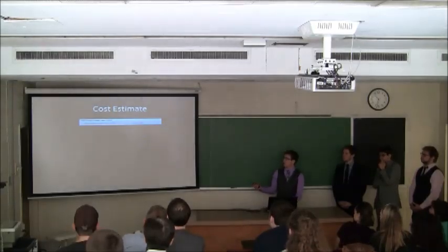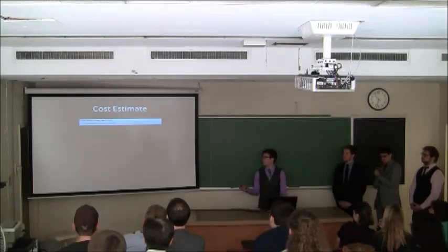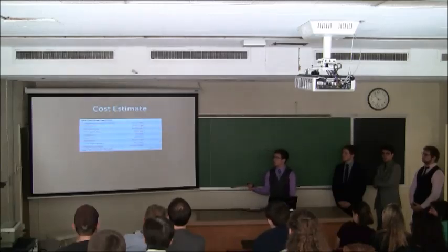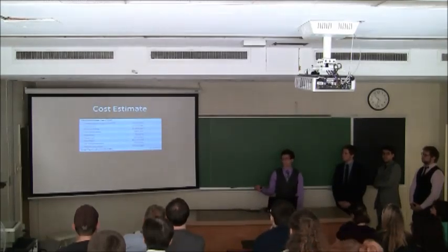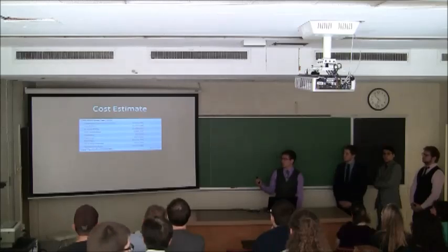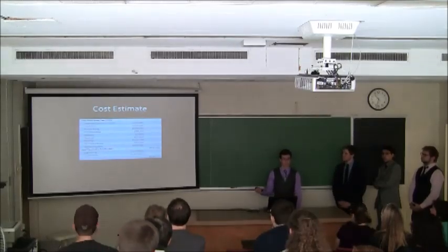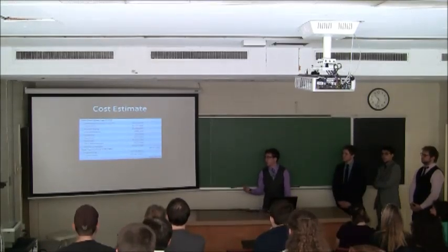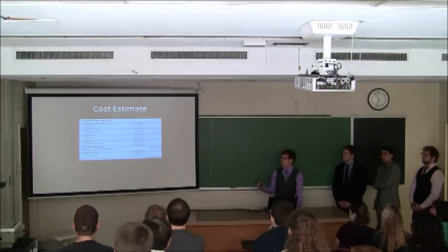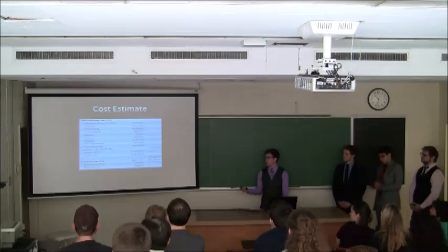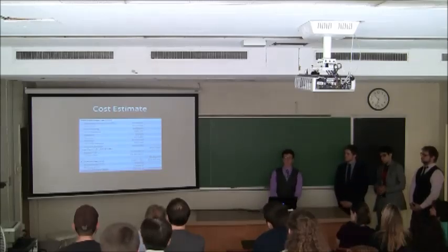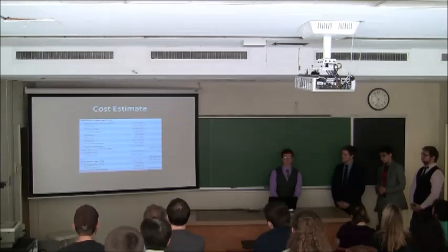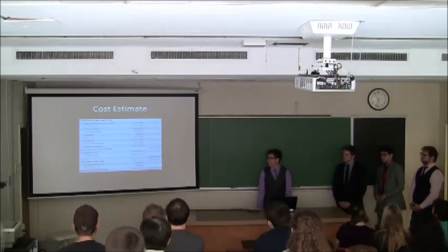So like I said, you start with your purchase cost of your equipment, which is $2.5 million. Multipliers bring this up to a total of $8.8 million, which was then used to calculate the indirect costs of the engineering and construction. This was a total of $5 million, which was added to our contractors' fees and our contingency finances. And we would require a direct fixed capital cost of $16.3 million to start this entire facility.